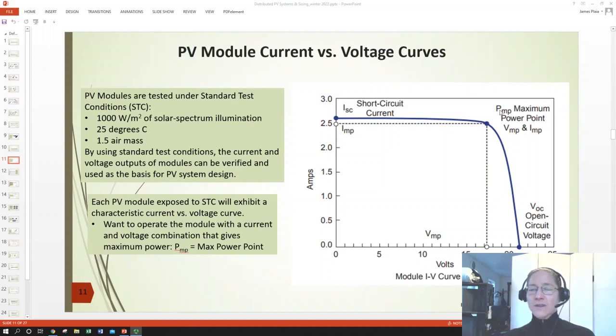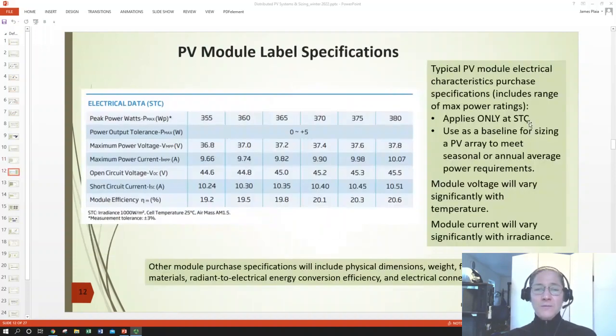And so both the maximum power, PMP, the VMP, and the IMP are all specific to the way that module is going to act at standard test conditions. So be warned when you're shopping. If you're going to be getting that panel a lot warmer or cooler, or be giving it a lot more photons, you could get a value that's much larger or smaller. But this gives you, again, a basis of how much power you can get from any given panel.